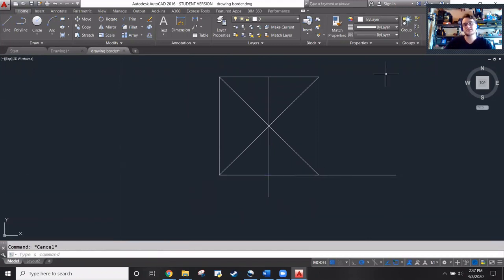Okay, so select this line and this bottom line, and then the body of the diode. And now type trim. By selecting all that, it's going to let us trim with definition to whatever's selected. So I can get rid of this and this and this and this and this. Not that, apparently, and this. Okay, cool. Now delete these and delete these. And now I have a decent drawing of a diode.